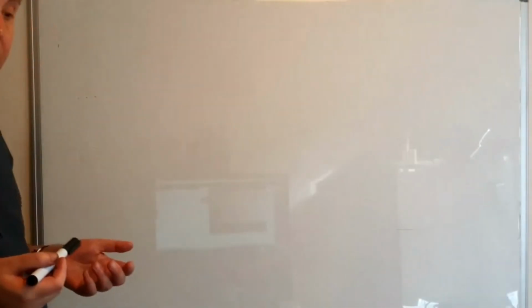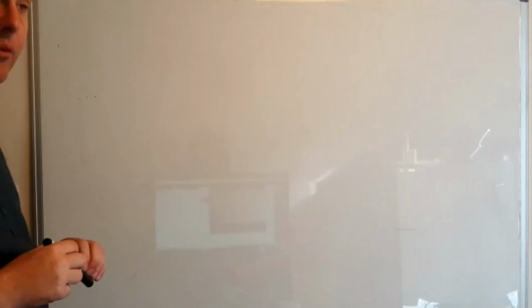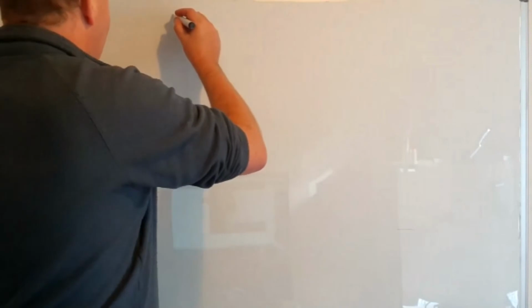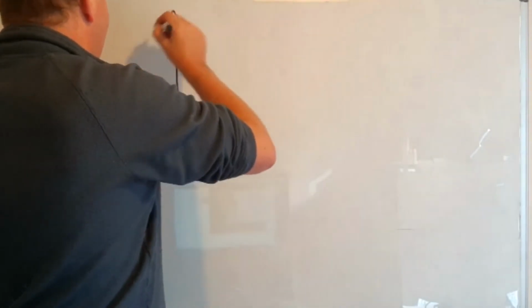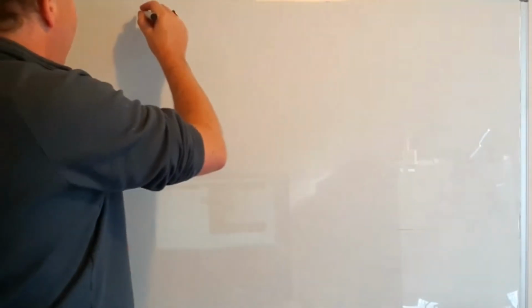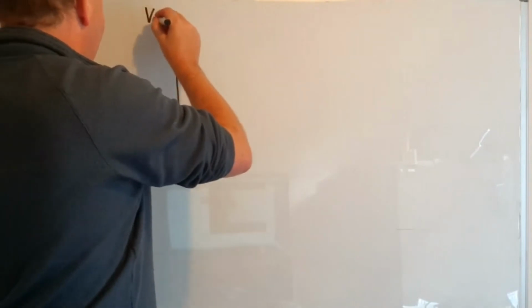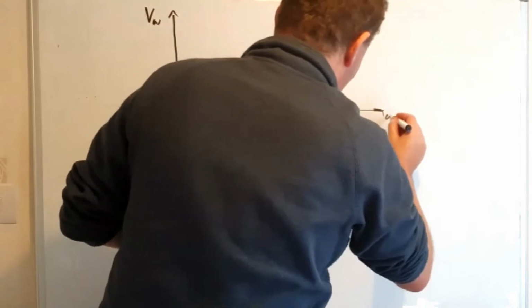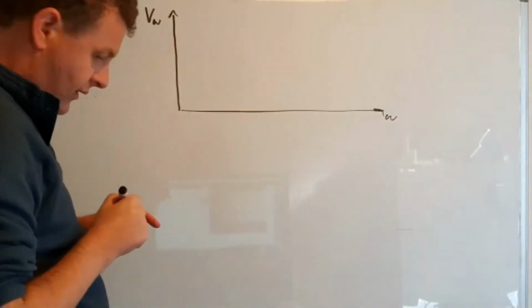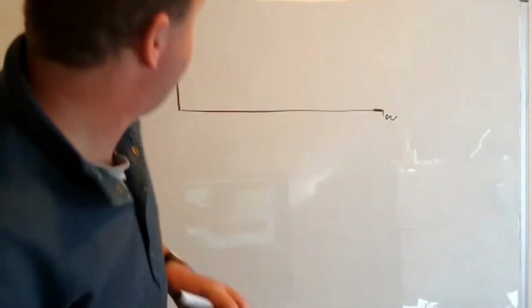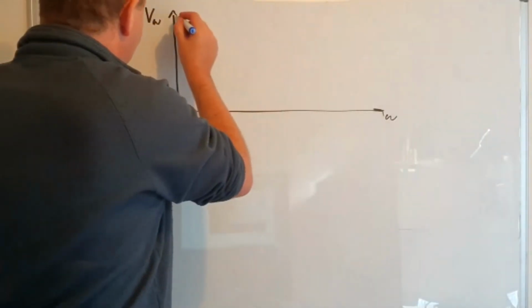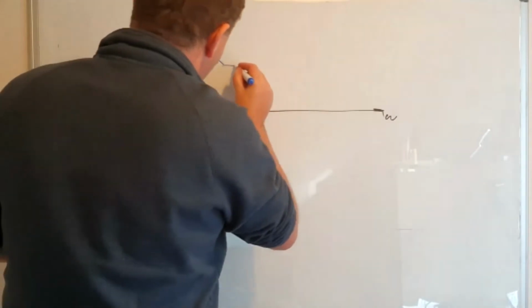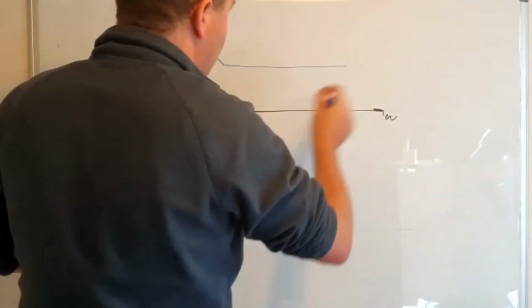So in the noise lectures, we're going to look at what goes on in terms of the noise sources in a typical lab. So we can draw a picture of the noise sources by looking at the amplitude of the signal, V, as a function of frequency. And what we see is that a typical noise spectrum has some 1 over f noise, and it goes flat with white noise.